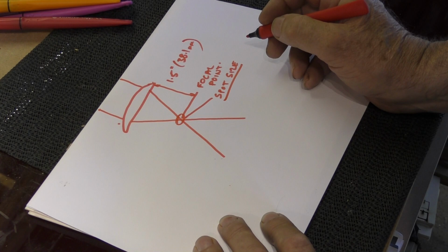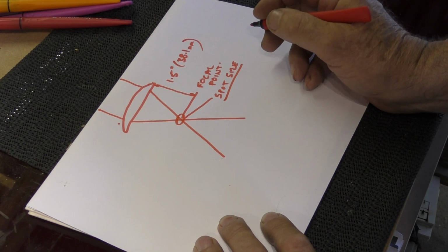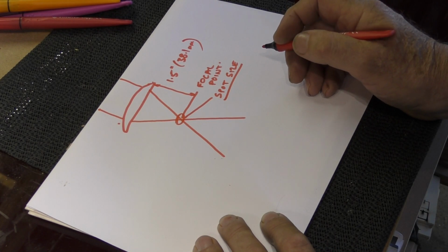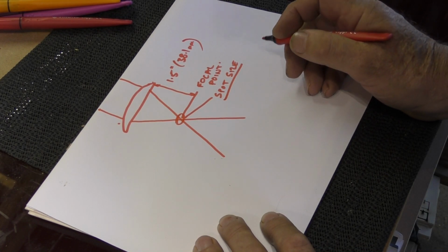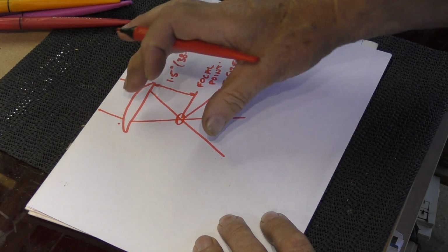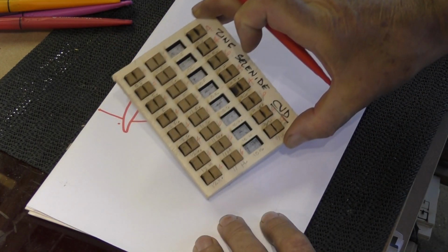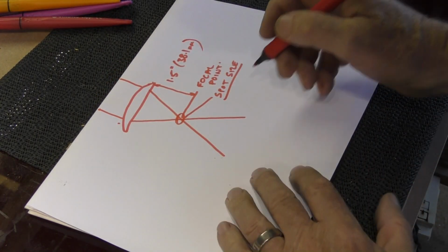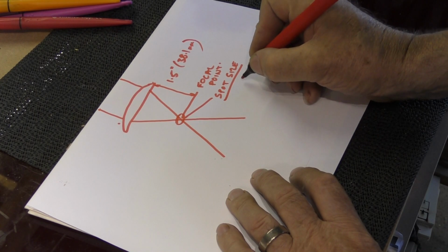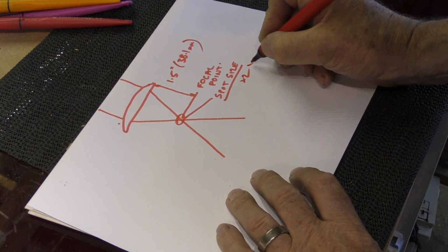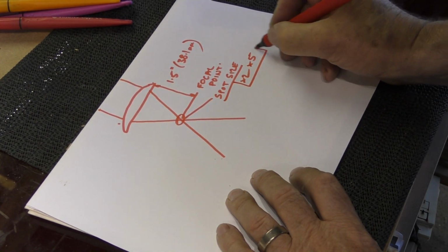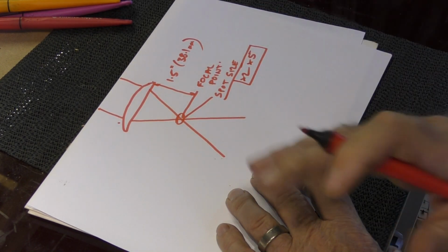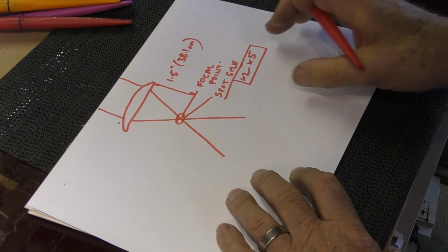All I can say to you is it is theoretical, because in practice, with all the tests and work that I've done plotting the energy density through the lenses, and also this current work where we've looked at things like the width of the beam entering and leaving, I can tell you that it's anything between ×2 and ×5 bigger than the theoretical spot size. So ignore what the book says and just live in the real world.